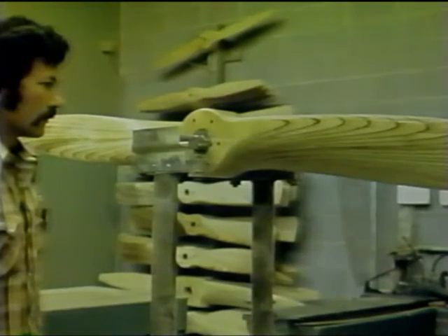Secondary balancing is accomplished before the stainless steel tipping is applied. Stainless steel tipping is hand-formed and secured with both rivets and screws to afford maximum strength and durability. With the screws and rivets secure, the propeller is now ready for the flushing operation.